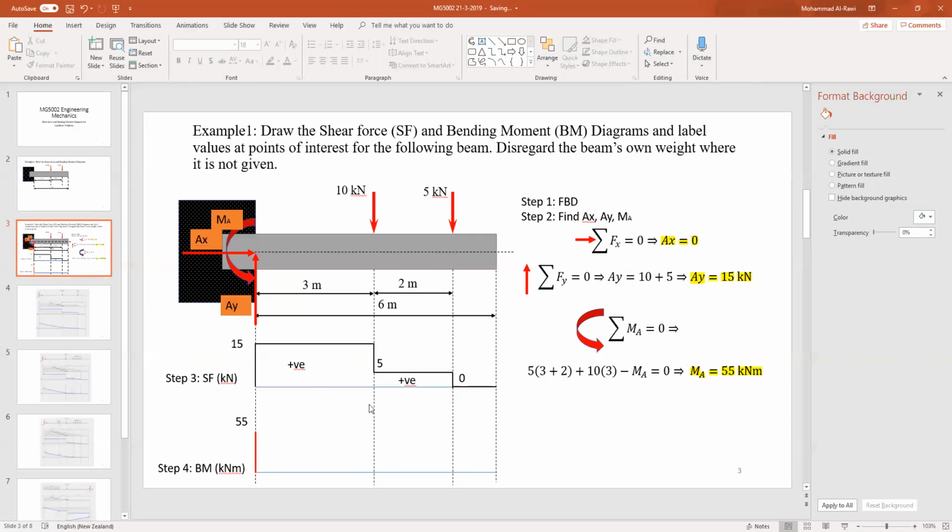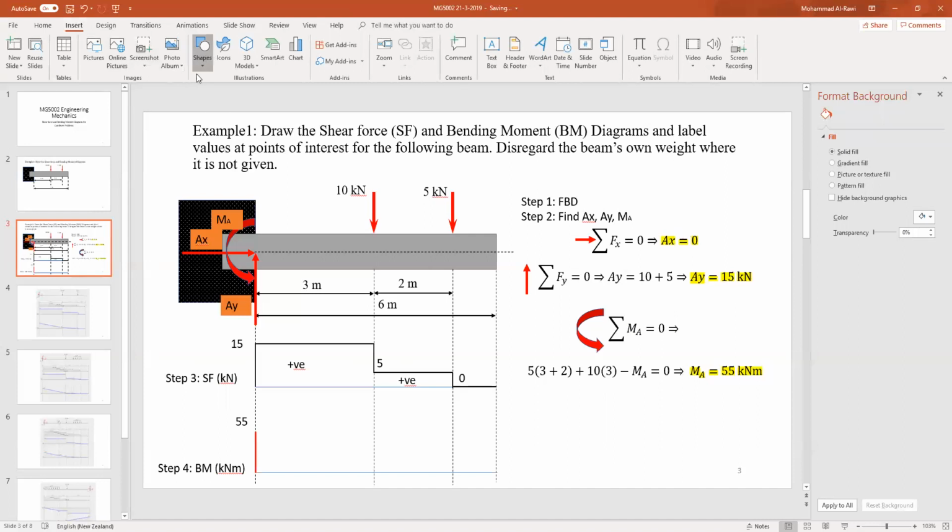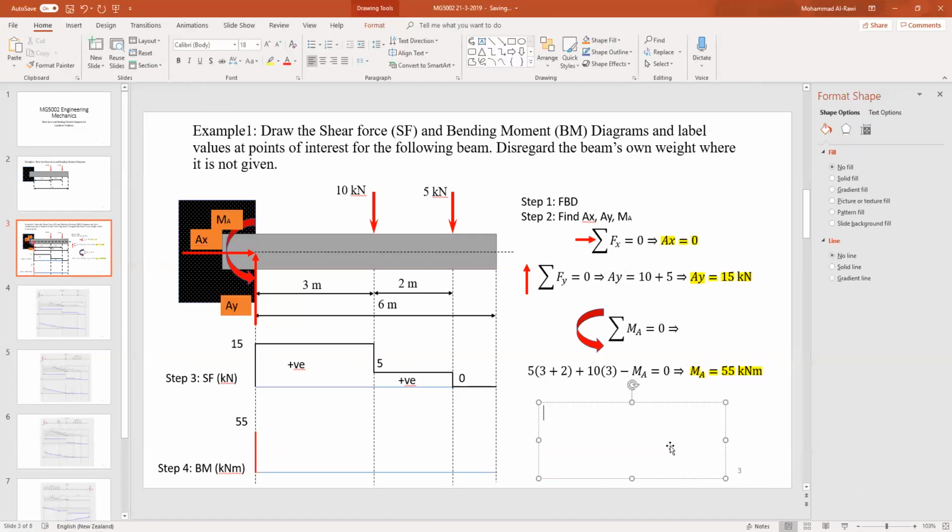Now, I need to determine that area. So I will write the equation for bending moments on the side so you can understand how we will perform the calculations. So I have 55, which is the highest bending moment we're getting here. And then we need to indicate how much we're going in the positive direction. But what's interesting here about cantilevers, which has confused many students, is that it's not adding anymore, because that's the maximum we started with. So if that one is 55, technically speaking, it's a moment going in the opposite direction, but it's giving me a value of 55.